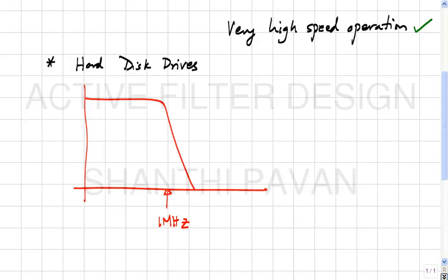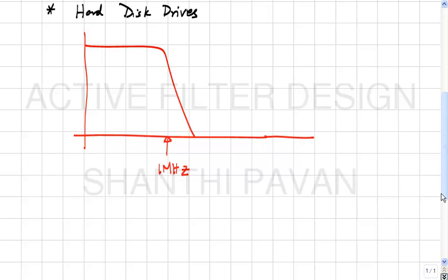But as we all know, all filters will fundamentally be non-linear, because the integrators use transistors, which are non-linear. So, it follows that the integrators will be non-linear. It is only a matter of degree, whether they are very non-linear or less so. Now, if you take a weakly nonlinear system and you put in 2 tones, let us say, for argument's sake, I will take a simple